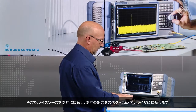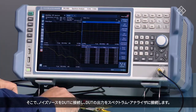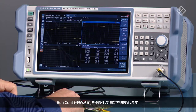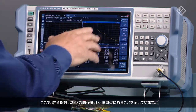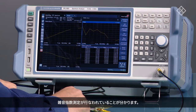So now we've connected our noise source up to the device under test and the output of the device under test up to the spectrum analyzer. So now we're just going to start making a measurement by selecting Run Continuous. And here we see that we have a noise figure between 2 and 3 and gain somewhere around 18 dB of gain. So we've made a noise figure measurement.